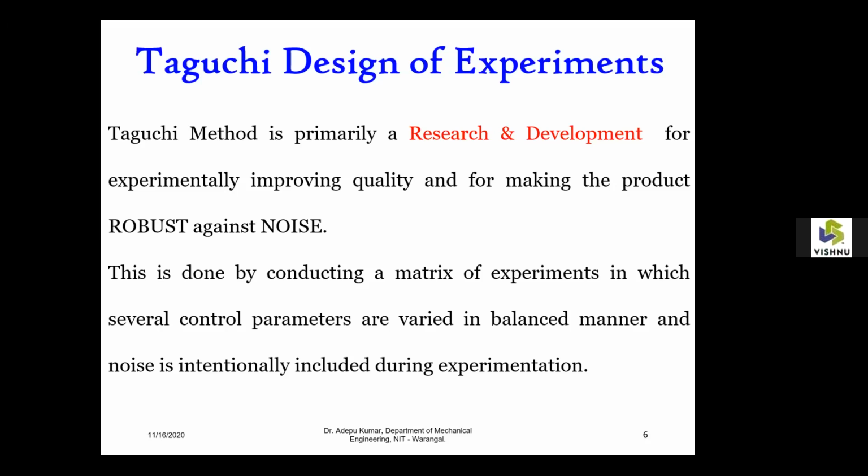If you are performing any machining operation using a lathe, you are giving inputs: speed, feed, and depth of cut. You are measuring the metal removal rate, for example. If you go on running the machine, after a certain time your performance is also going to change.